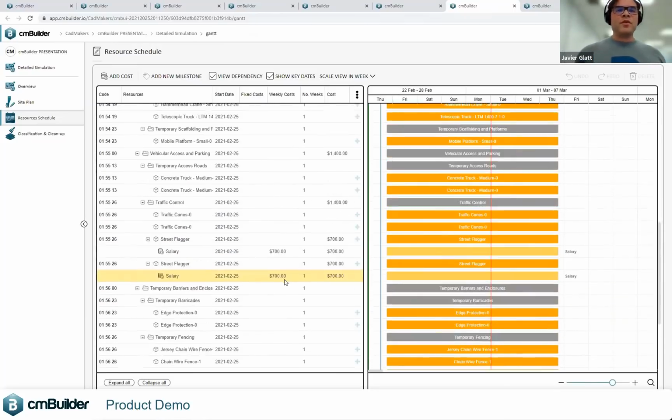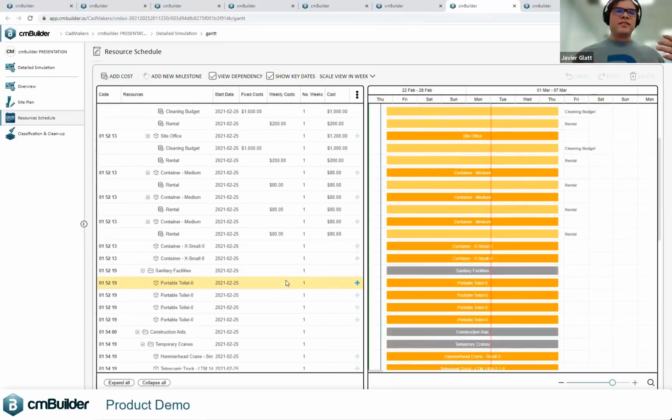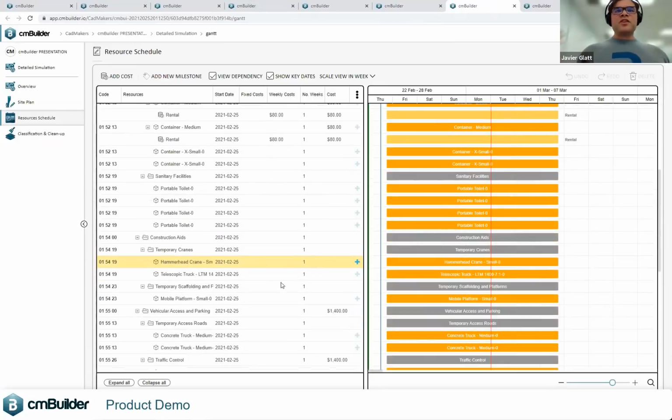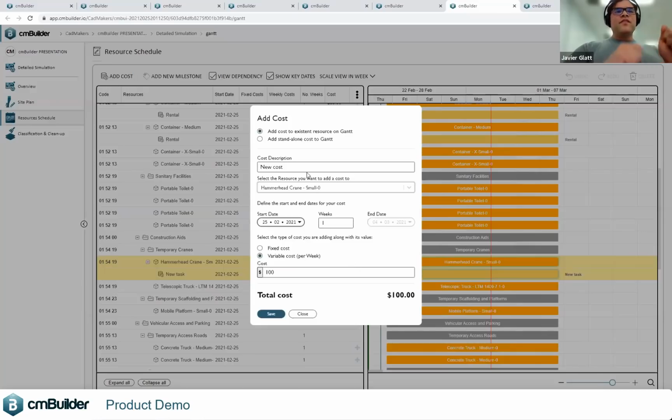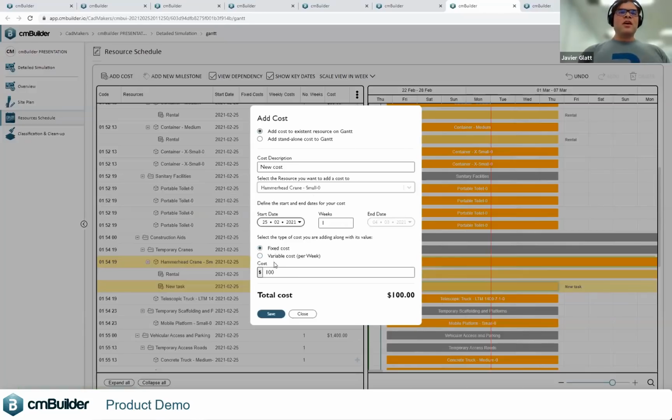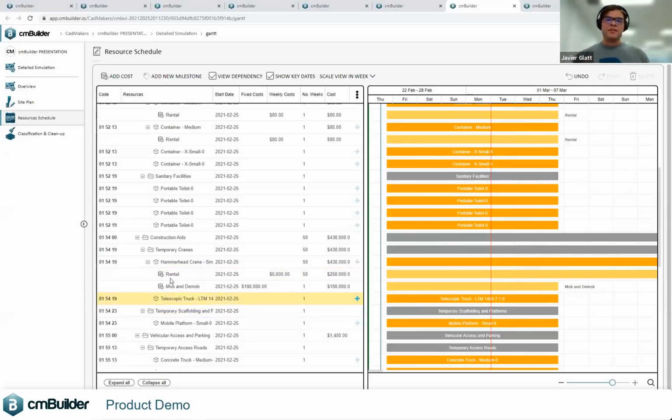I remember talking with Tyler a long time ago when they were planning jobs at an early stage, you say, I need a trailer or two, and they're $500 a month. And how many months do I need it for? I'm not sure yet, right? You can start really saying, okay, I need 5 trailers for $500 a month for 18 months, right? And really add that up. And then every time you use that resource in any project, it goes in the database. So next time you're building an 18-story mixed use, an 18-story hybrid mass timber concrete building, all your actual costs, you're going to be able to use in the next pre-planning, right? So you're using the data that's coming from previous jobs to inform the next planning job, to understand and track these costs, okay?